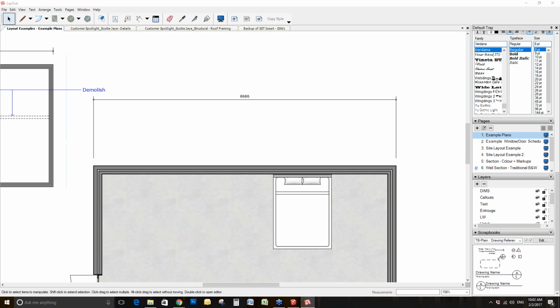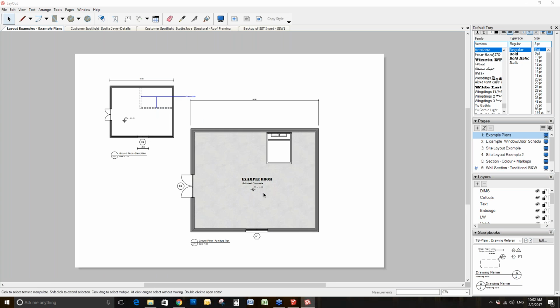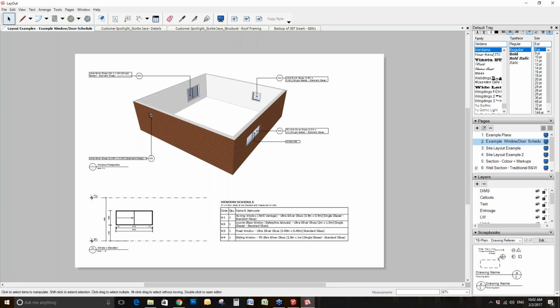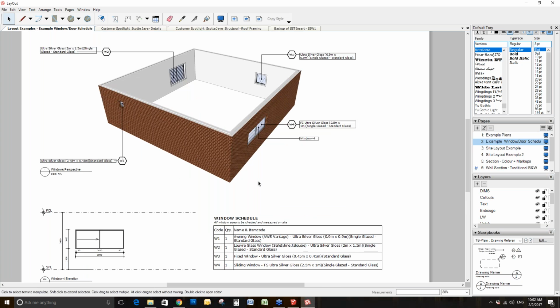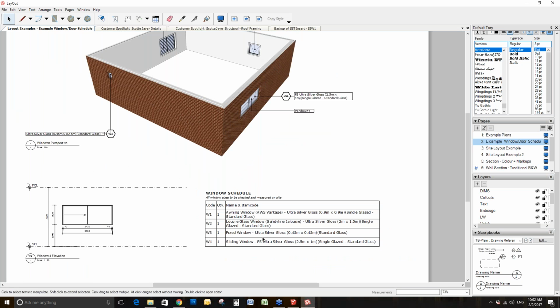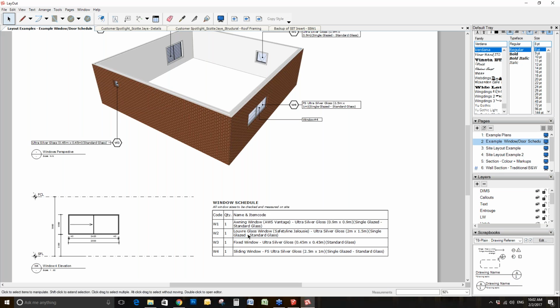I have another question about how do you connect the window and door numbers from the 3D model to the window schedule. At the moment, yes, you need to, in the CSV file that I created, if I go into that, when I exported my takeoff with my window schedule, I simply went into my Excel document and added the different ones, but it's done in order. So it knows what is number 1, number 2, number 3, so you simply know that that's the top and that's the bottom. Unless you reorder them, and then obviously once you've updated your CSV, if anything changes, then it's a live link. So it's not really that much extra work.